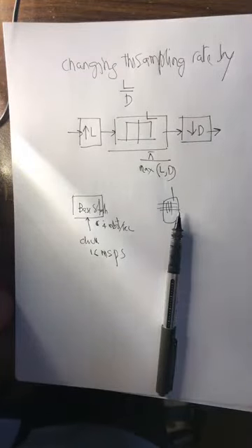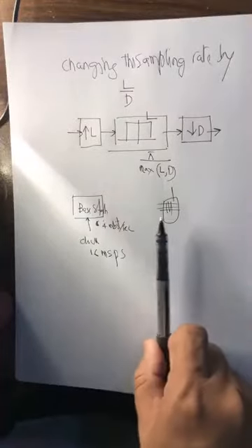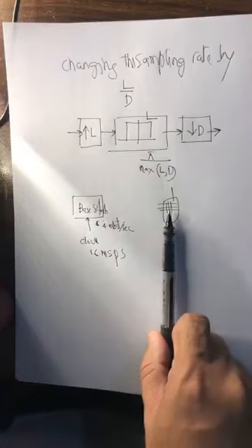Not only that, it'll basically disturb all the synchronization. A sample from the previous bit will get into the next bit, and all kinds of issues will happen, because there is absolutely no way for the crystal which works in the base station to match the crystal that is in your mobile phone. Absolutely no way. They are from different vendors. They have a little difference, because you cannot exactly match them, no matter how little the difference is.